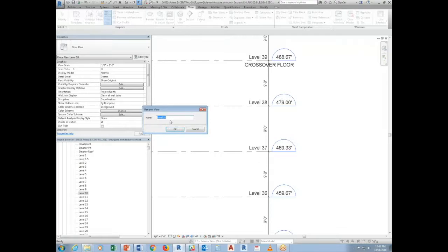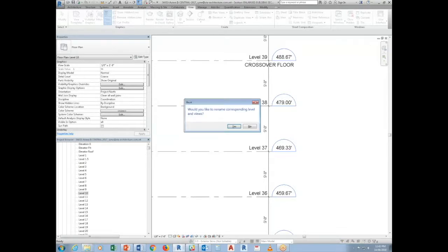So how do you know if this view is a source view? Let's say you say temp, or you could say this is working, right? Level 10 working. It will tell you this. This is how you tell if it's a source view. What I mean by source view is that it's the first view inside Revit. Whenever there's the first view in Revit, it always will display this particular message. Now, once you delete this, Revit will move on to the next view that was created.